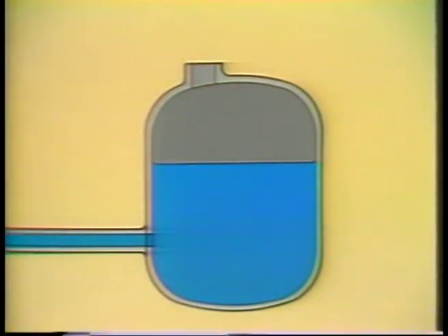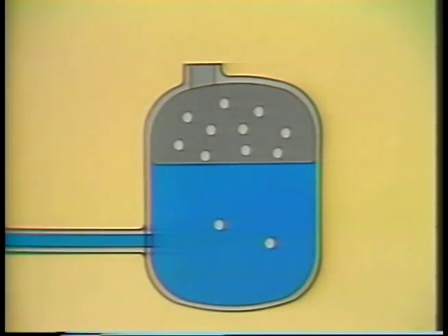Let's say the tank contains water, and we're concerned about corrosion caused by oxygen in the water. Since storage tanks are almost never completely filled with water, the empty space at the top will be filled with air. Air contains oxygen, and some of the oxygen will be absorbed by the water. Oxygen in the water causes a problem, namely corrosion. And the greater the oxygen content of the water, the greater the tendency for metal parts to corrode.